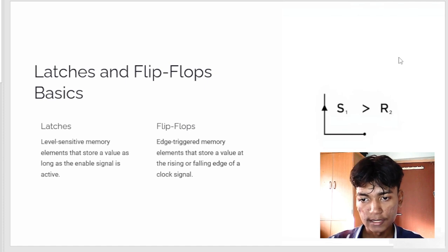Latches and flip-flop basics. Latches: level sensitive memory elements that store a value as long as the enable signal is active. Flip-flops: edge triggered memory elements that store a value at the rising or falling edge of a clock signal.